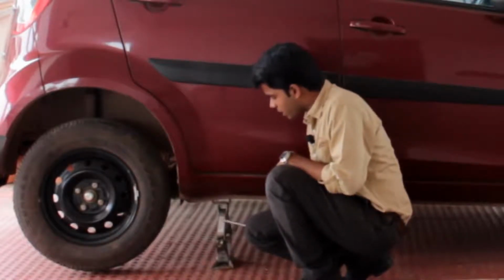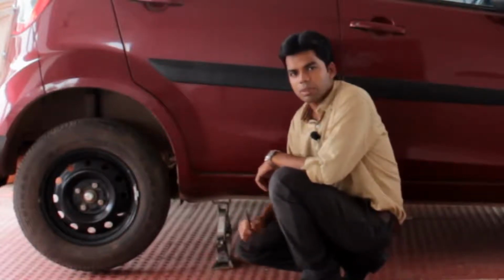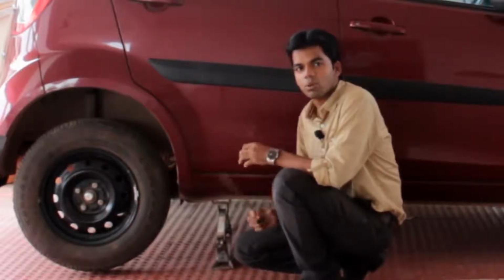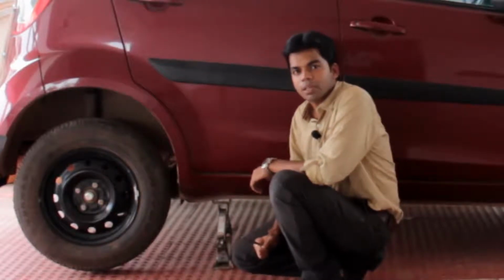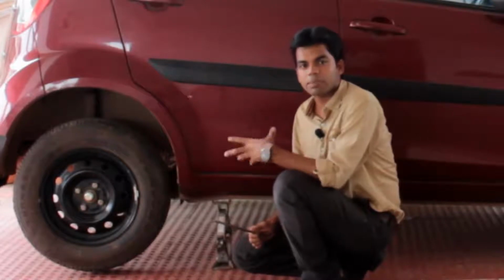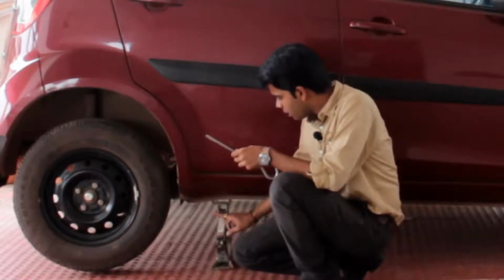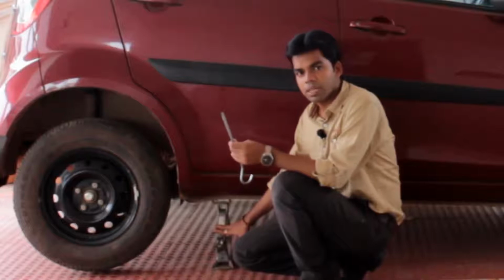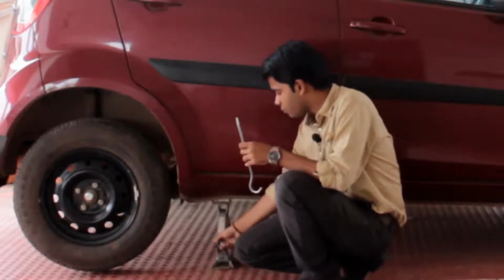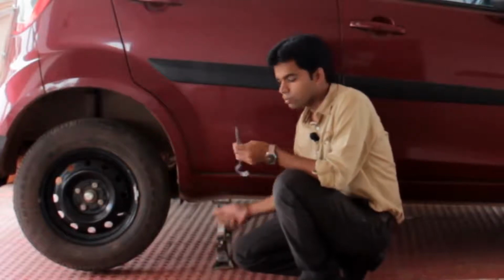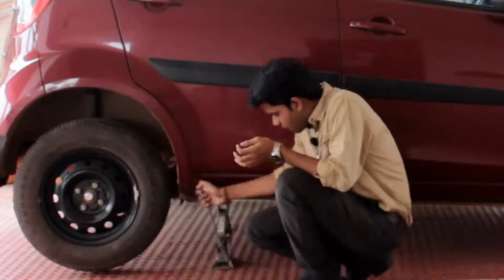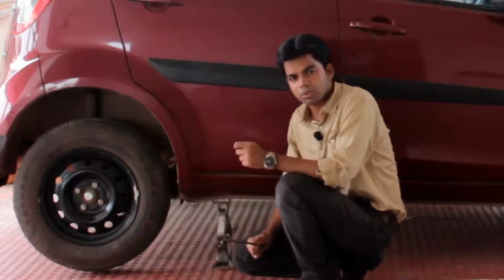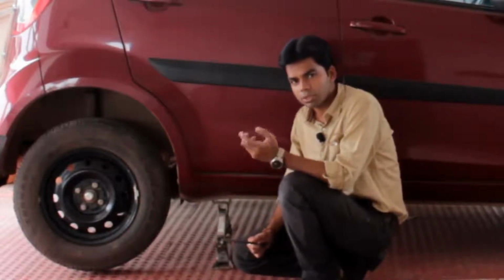Such a device is known as a simple machine, a device which multiplies the force. I am applying a very little force, and that is multiplied in order to lift the weight of this whole car. Such a device is known as a simple lifting machine. When I put two simple machines together, it becomes a compound machine. For example, in this device, the first machine is the screw jack, which in itself is a machine. The second machine is this lever, because if I apply the force from here, it will be very difficult. So I put a lever on this and apply a force, and it becomes very easy. Such a device, in which two or more simple machines are used, is known as a compound machine.